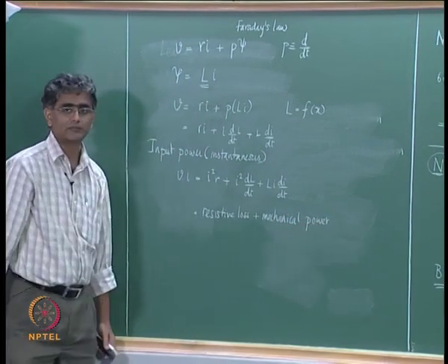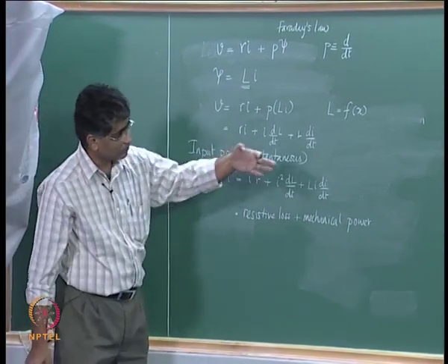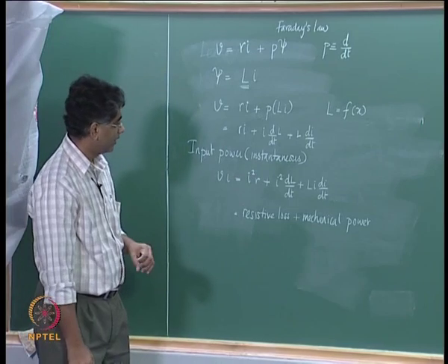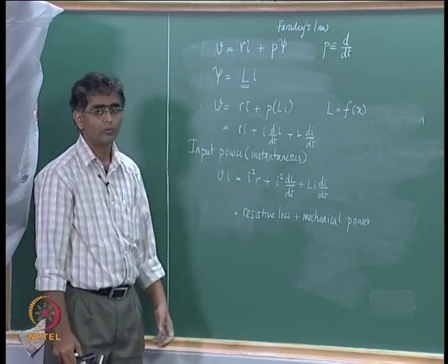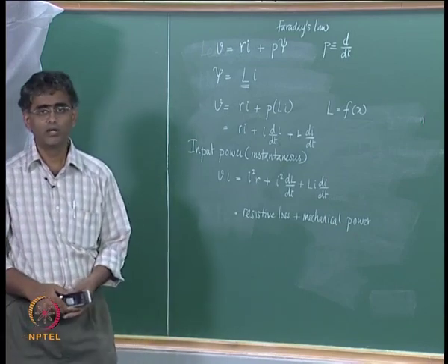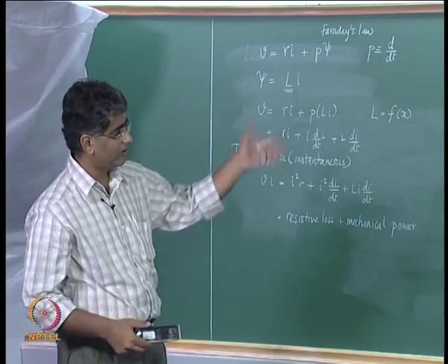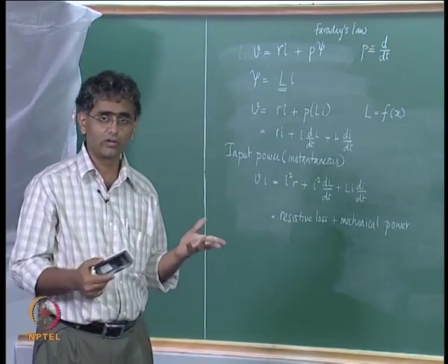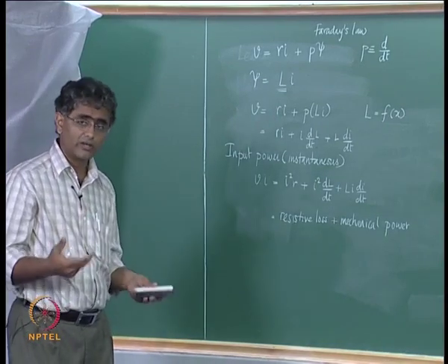and then what else? Now when this rod is going to move, we expect the variable I to change, input current is going to change, and we know that if input current is going to change, the magnetic field associated with that is also going to change, and field is nothing but stored energy.